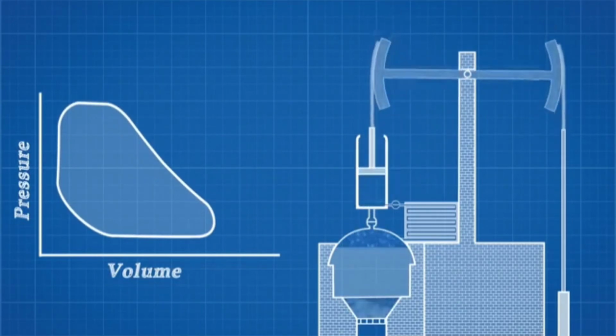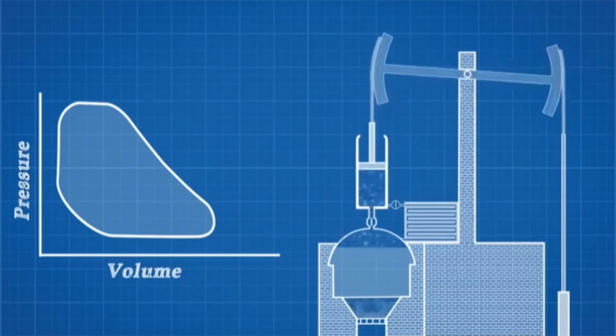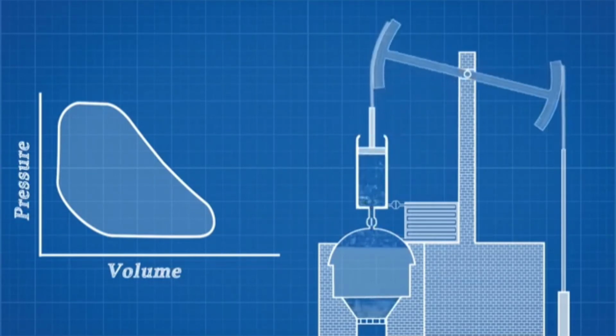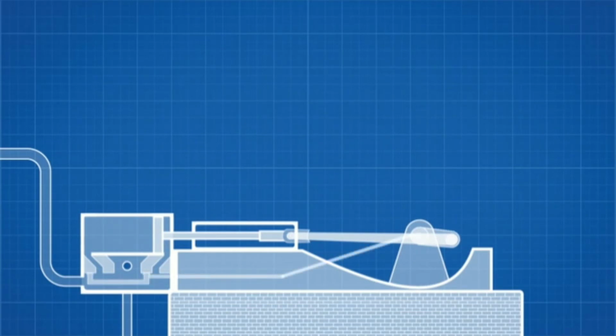We are starting to see a steam engine capable of sparking an industrial revolution, but this reciprocating motion isn't much use for most applications, especially with this flexible chain connecting them. What we need is rotational motion, which requires a different setup. To convert this linear motion to rotational motion, we need a crankshaft and connecting rod. We have turned this piston cylinder on its side, so atmospheric pressure can no longer force the piston back down, so we need to use steam on the return stroke. This requires a control valve to control when the steam enters and leaves each side of the cylinder. The valve is controlled by a cam.